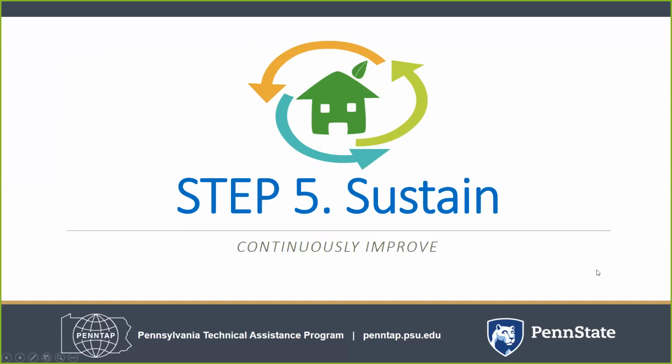Step 5. Now that you've done BRT and you've implemented projects, you want to improve continuously. You can achieve this in many ways. Consider energy management systems for your facility. Continue to benchmark using Portfolio Manager and the Asset Score tool. Continue forward with preventative maintenance programs. Upgrade energy-saving projects when you can, and tell your story about the savings from your current BRT projects. This encourages behavioral change with the occupants of the building and inspires department heads to fund future projects.